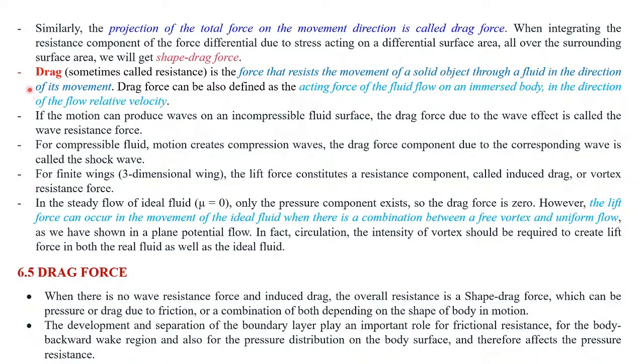So we show here drag, sometimes called resistance, is a force that resists movement of a solid body through a fluid, in the same direction as but opposite to the movement. Drag force can also be defined as the acting force of the fluid flow on an immersed body in the direction of the flow relative velocity.